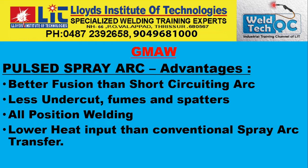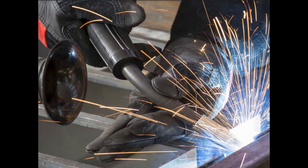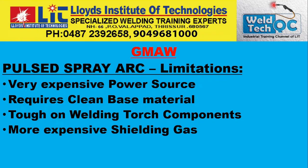Again, your power source, the welding machine, will be a modified, computer programmed special machine, which is very expensive, and it requires a clean base material. Rusty, oily metal is tough to weld, and it is very tough on welding torch components, its consumables. You will have to keep changing them every now and then. And for your shielding gas, you are not using CO2; mostly you are using argon, which is expensive.